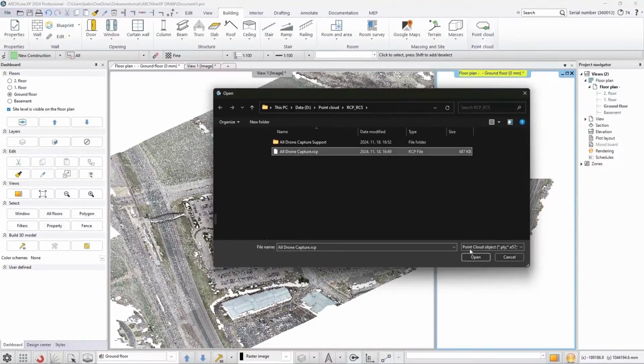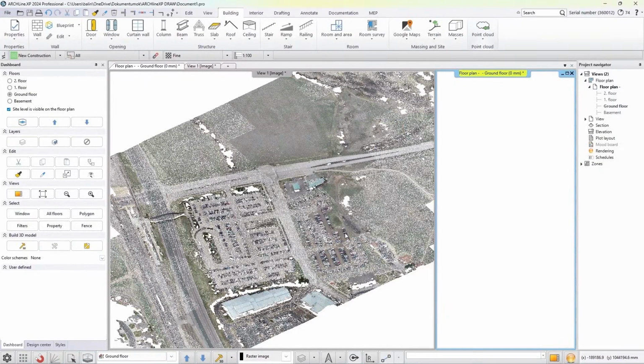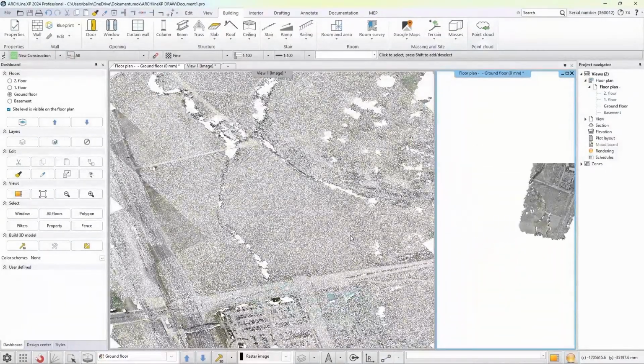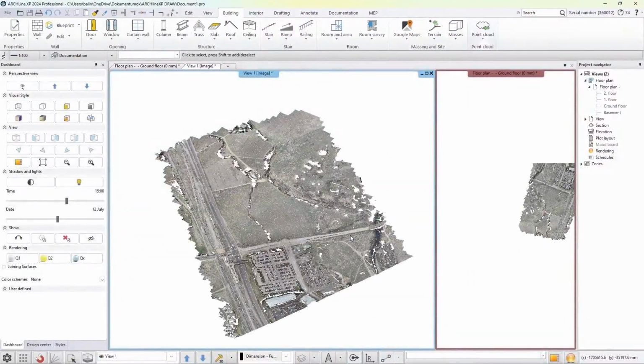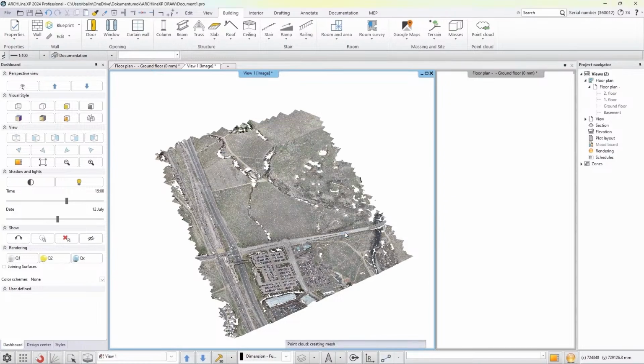As the planning process evolves, you can activate different parts of the Recap point cloud, thus only the required RCS files are displayed. This is a useful method to differentiate between the included buildings or between the rooms of a building.